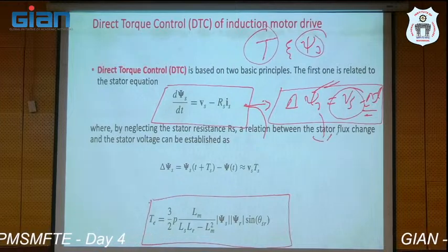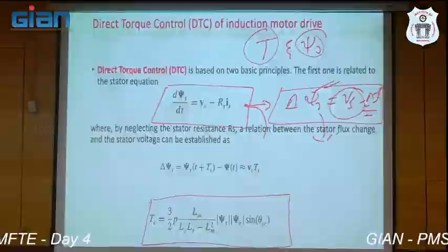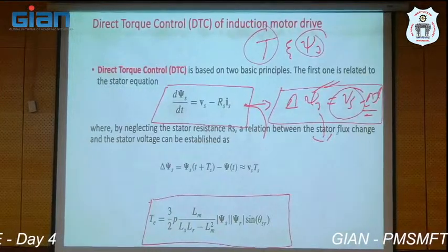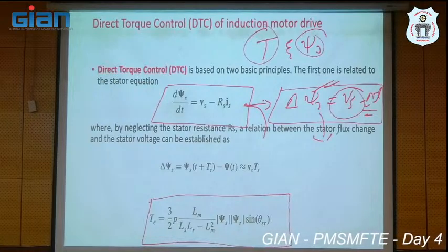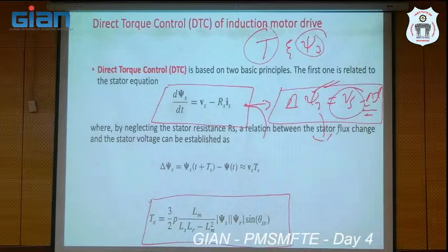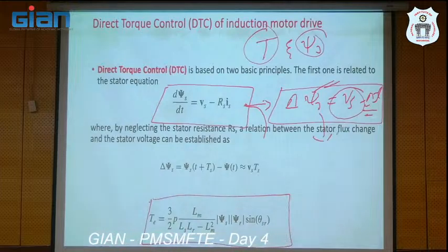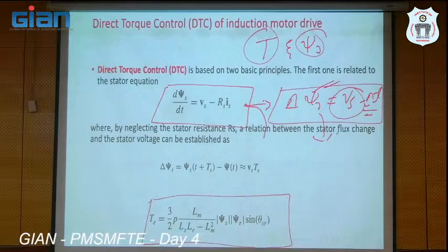By exciting the synchronous machine under no load condition more than the rated value, it will produce reactive power, so the voltage will balance and the grid voltage profile will improve. That is what we have studied in power systems or electrical machines also, right? You got my point, right?